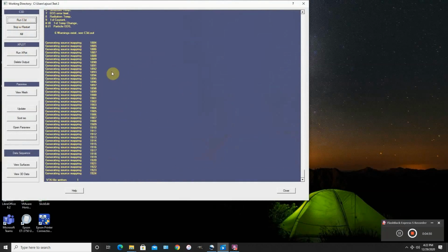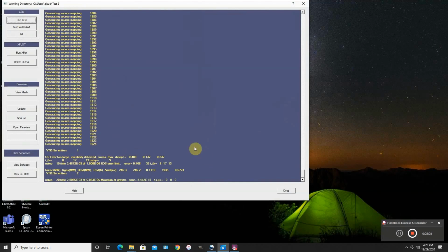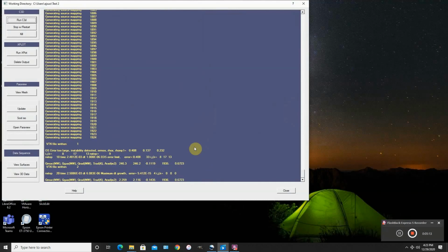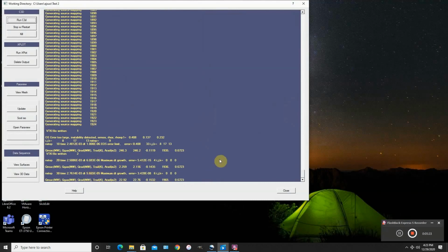Here it's mapping the 1D subgrid to the top of the stack. So these are the source terms. It looks like it's got that many, one for each computational cell up there. So it looks like it's a sudden onset, so it's having some difficulty getting started. There are some instabilities associated with the high-speed flow. But it looks to me like it should just start up. The time step is increasing. It'll go up to the max time step of 1 millisecond after a couple of minutes.